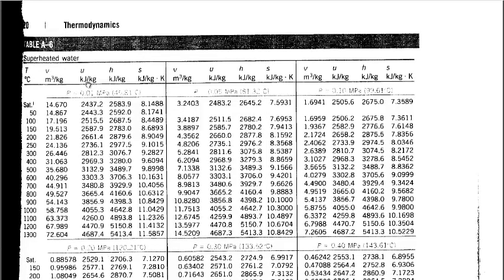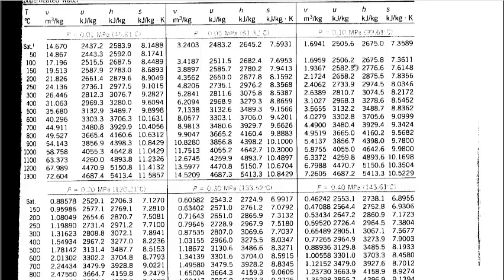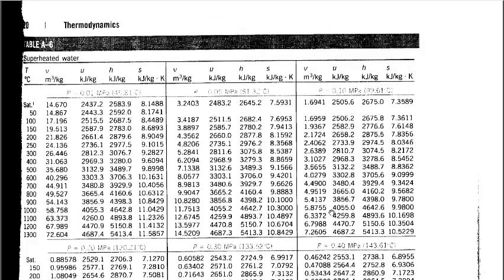So this is a pressure subtable where all of this data corresponds to a pressure of 10 kPa, 0.01 megapascals. And all of the data in this pressure subtable correspond to a pressure of 50 kPa, 0.05 megapascals, okay? So on and so forth, 100 kPa, 200 kPa, 300 kPa, 400 kPa, and it's the same story as you flip through the next few pages of table A6.